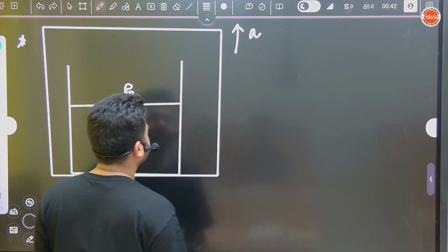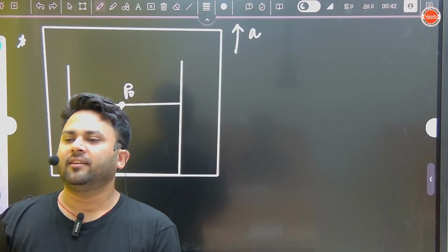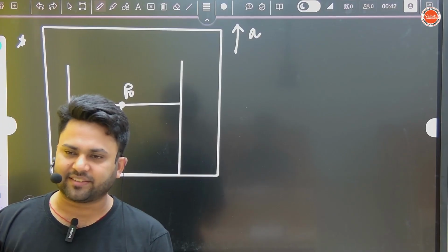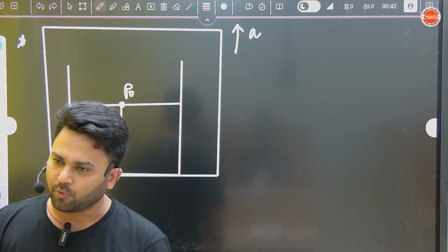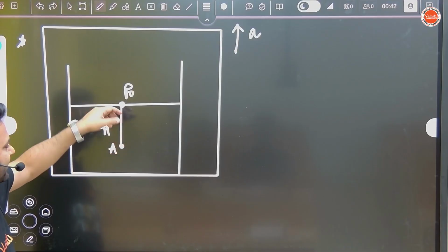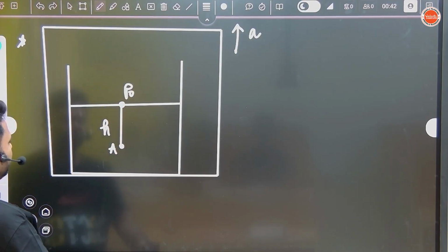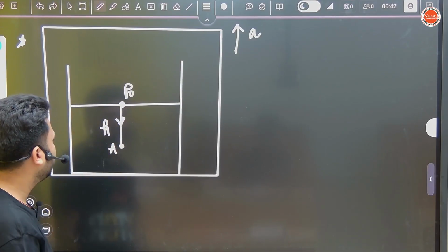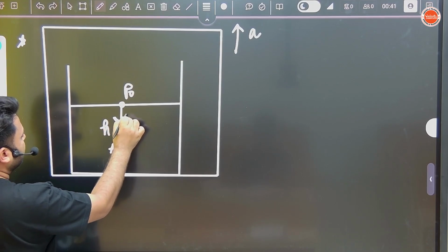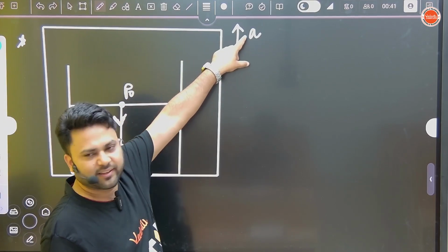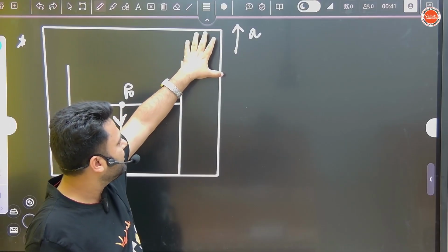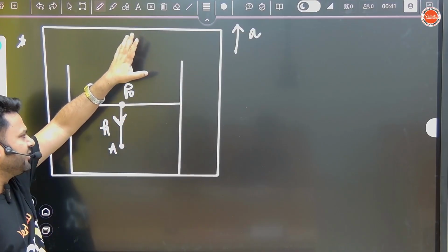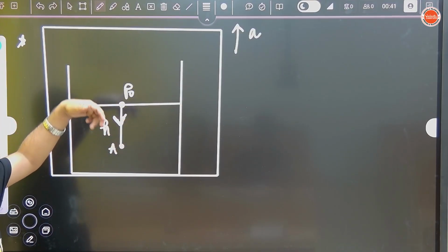So see how to write. First of all, you have to see in which direction acceleration is there, and in the direction in which acceleration is there, that direction pressure will be more. So one of the accelerations is g downward. If the container, means lift, is moving with A acceleration, the fluid you will take in the opposite direction.